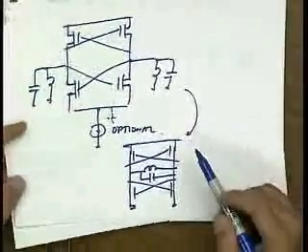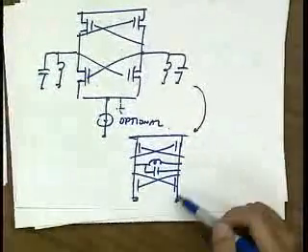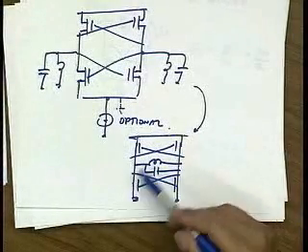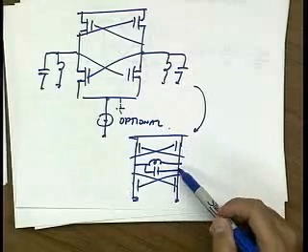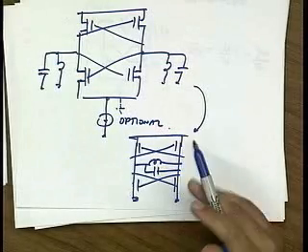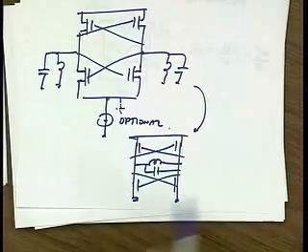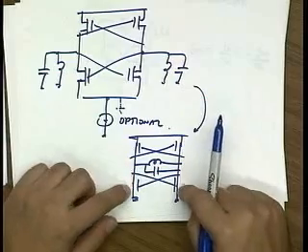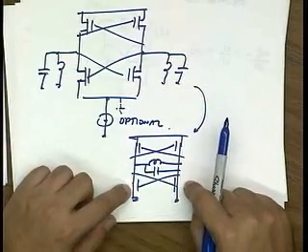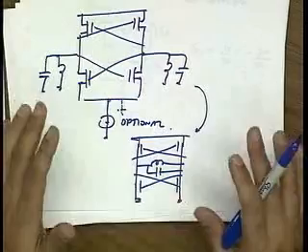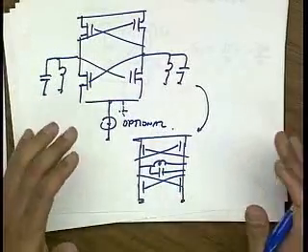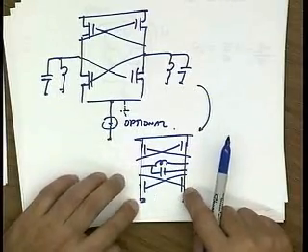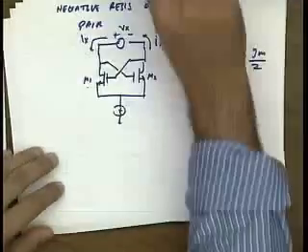That's because a MOS amplifier is much more linear, and so you can have very large voltage swings here and still not compress this device. In a bipolar amplifier, we know a differential pair has a linear swing of around 120 millivolts or so. So if the differential swing is bigger than a couple hundred millivolts, it drives this device into deep compression, and the oscillation amplitude would basically stop. So in order to get a larger oscillation amplitude, I would divide the output before I apply it to the circuit. So that's the reason why we use that cap feedback.